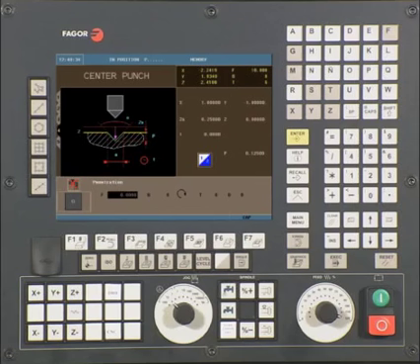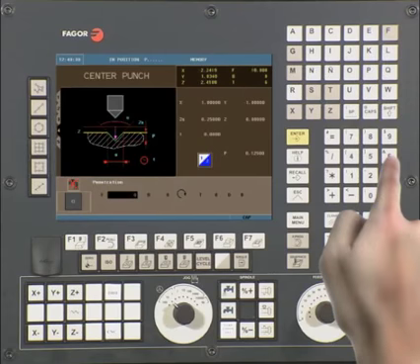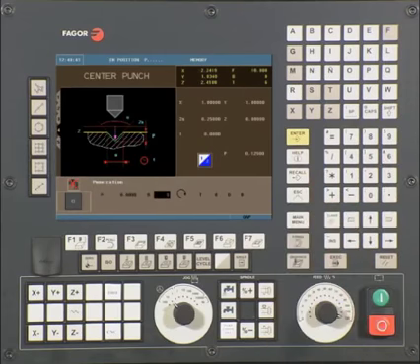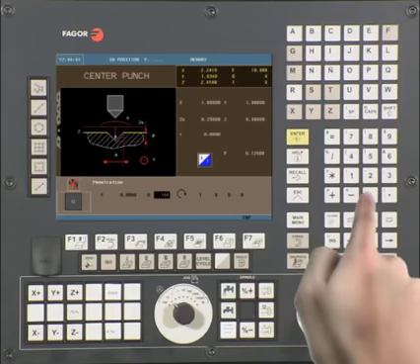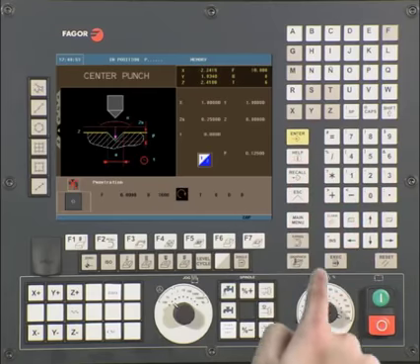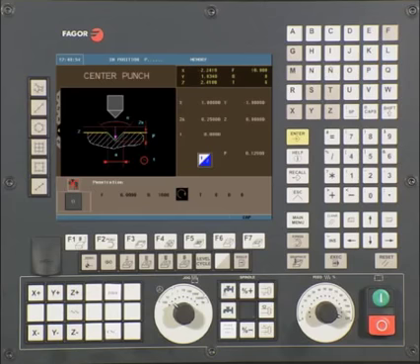F. This is your roughing feed rate along the axis. In this example, we are using a value of 6 inches per minute. Press enter to continue. S. This is your spindle speed. In this example, we are using a value of 1600 RPMs. Press enter to continue. Use the 1/2 key to select if you want spindle to turn clockwise or counterclockwise.